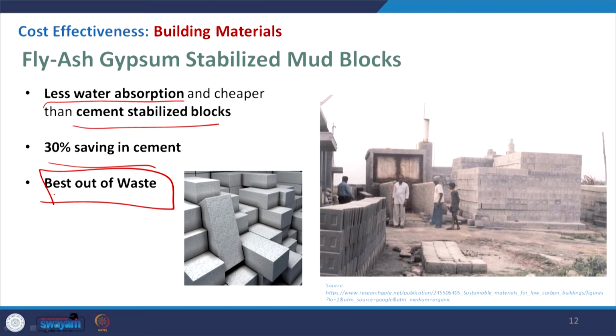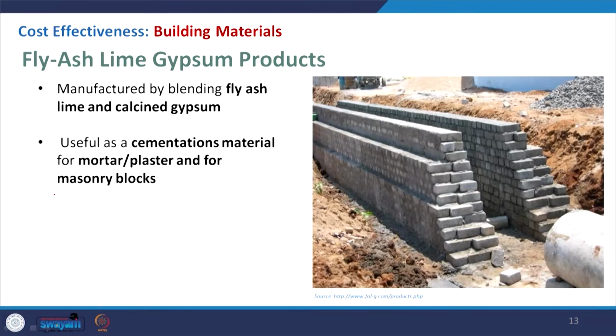Whenever the fly ash, which is basically waste, is used, it has good strength that can be used even if it is not load bearing. Now, in the case of the frame structure, most of the structures are concrete frame structures. So, this can be used as a partition wall or the external wall or sometimes even for the foundation or for low cost construction.